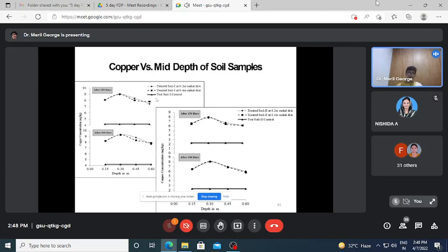Diffusive transport in soil is slower than diffusive transport in free solution because of the reduced cross-sectional area of flow. So we can conclude that due to the gravitational force and diffusive mechanism, the test soils at a depth of 0.3 meter will be more highly influenced by chemicals in leachate than at the other depths.